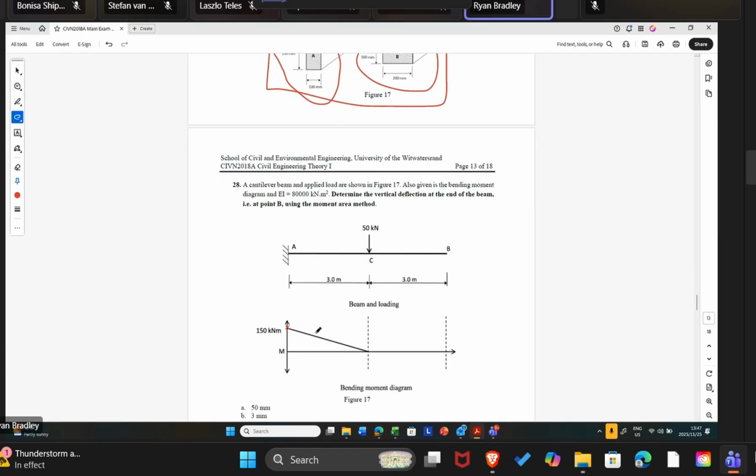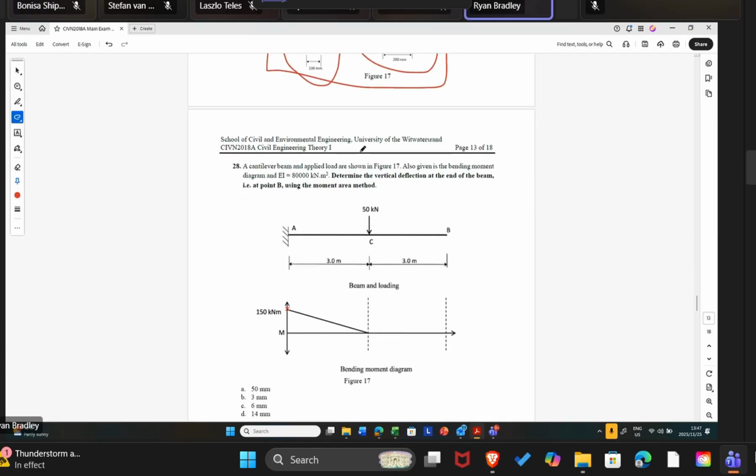Okay. And here we have a question asking for the displacement in the member. This is actually the final thing we discussed in that class, where the deflection in a beam like this, we can use a very simple method to work out the displacements or deflections. We can use more complex equations for more complex structures, but here we have a very simple structure, a cantilever. We all know if you take your ruler and apply a force to a cantilever, it is going to deflect down like this.